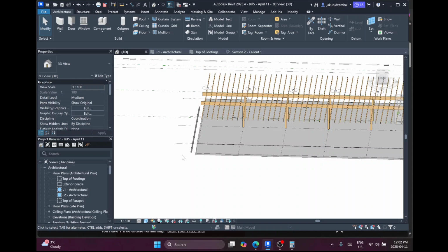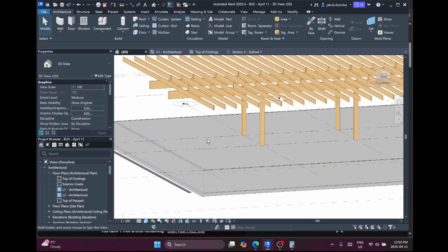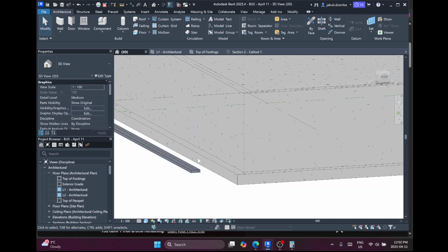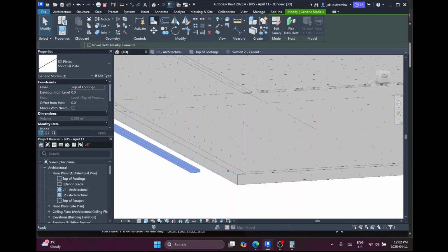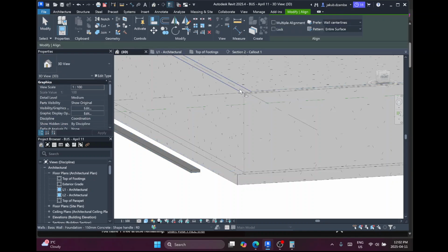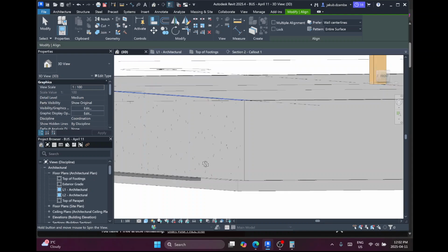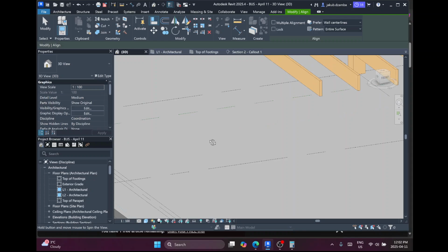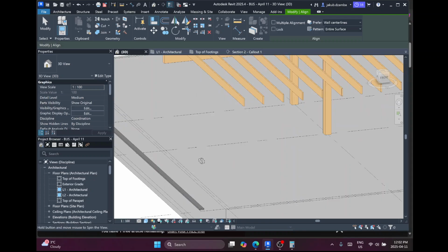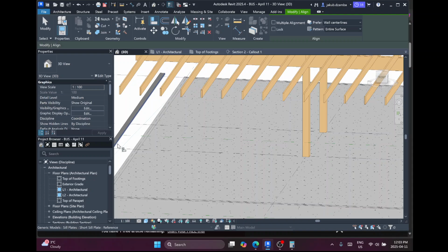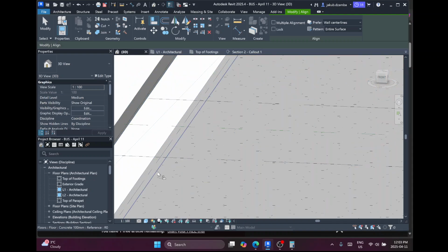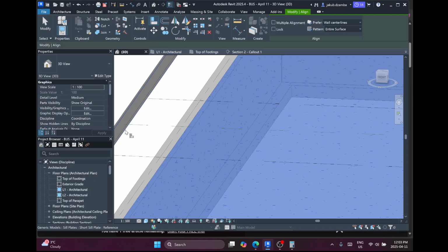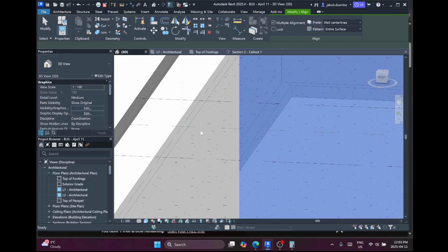There's a number of ways you can do this. I find sometimes this is the quickest. So what I would like first, I'm going to use the align button. So I'm going to click this, align. I want to align it to the top face of this, and I want to align the bottom face of this to that. So height, we're good now. Here, I would like to align this face to this short guy here. Wrong, something wrong.